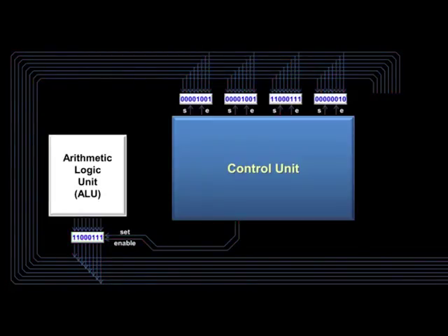The 4 registers at the top are just used for storing numbers between operations, so they have output wires that go directly back onto the bus. So now we have moved a number from one register to another just by turning some wires on and off. That's the advantage of the bus, easily moving numbers between components. The disadvantage of the bus is that you can only have one number on it at a time. Because of this limitation, the arithmetic logic unit uses a temporary register for input B.